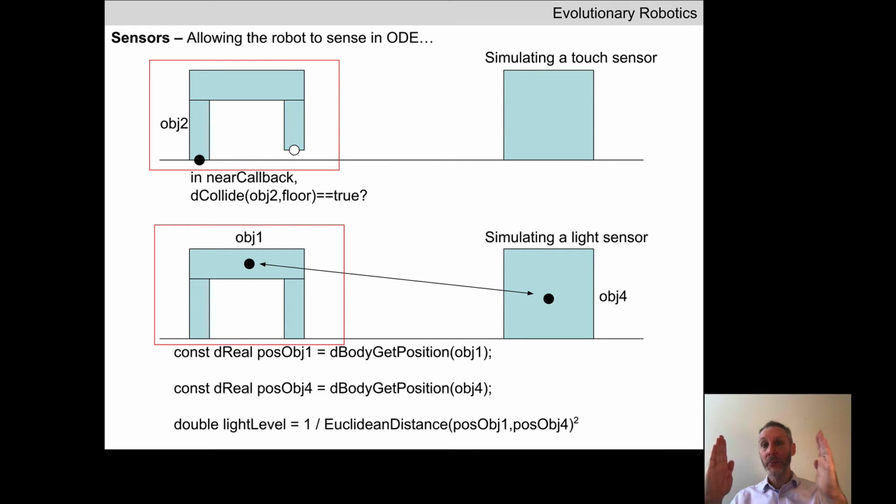So as the robot approaches the light, the distance from the robot to the light source is getting smaller, which means the denominator is getting smaller, which means the amount of light is getting larger. The amount of light detected by the light sensor is increasing quadratically as the distance to the object shrinks. Or alternatively, if the robot is moving away from the light source, the amount of light that the robot is detecting is decreasing quadratically. Why are we raising anything to the 2nd power? Any physics students here?